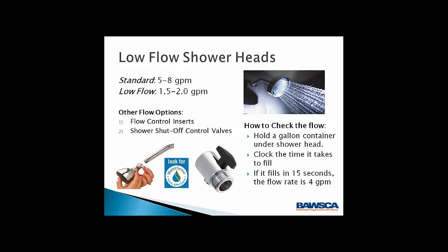If you're not sure if your shower is using a low-flow shower head or not, there's a simple test you can do to determine. You simply take a gallon container, hold it under the shower head, and clock the time it takes to fill. So if it fills your container in 15 seconds, then you know that your flow rate is 4 gallons per minute.